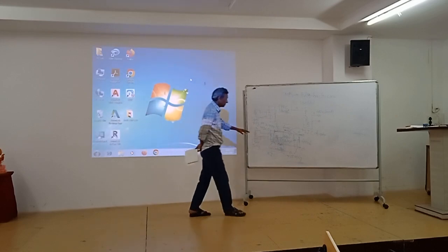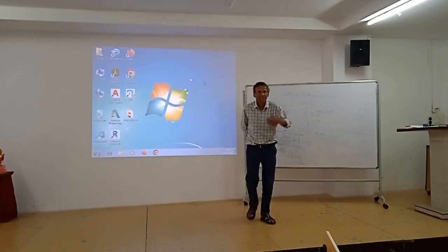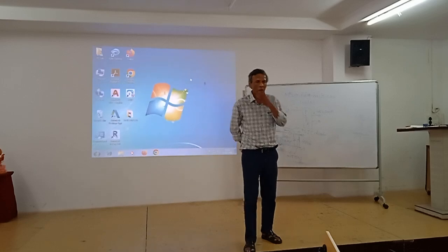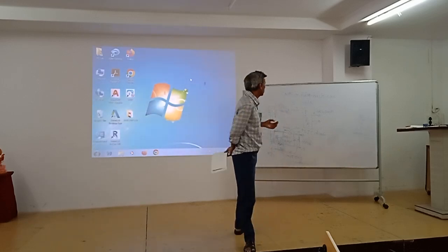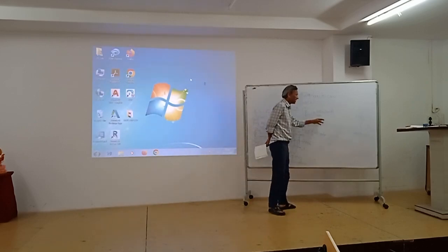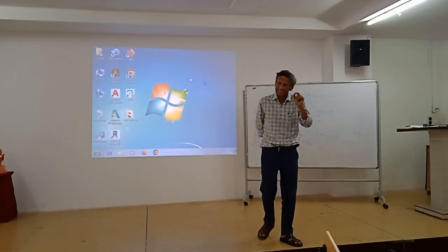So now we have gone for this. Suppose the DC link is relatively stable. Now we have to have 48 volt from this. Even if this is not very stable, 48 has to be theoretically stable because all the brushless motors are rated at 48.